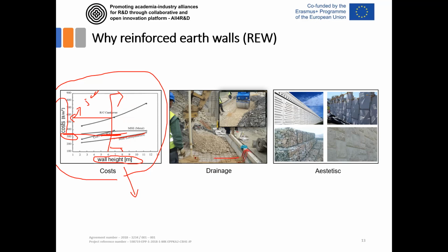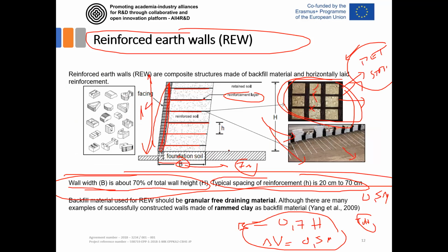Here is an example of reinforcement, backfilling, and compaction of the material. The wall is constructed from the bottom up. So you apply facing elements and reinforcement, and then backfill it. Once again, a second layer, and then backfilling. One additional layer, and backfill it, and so on from bottom to the top.